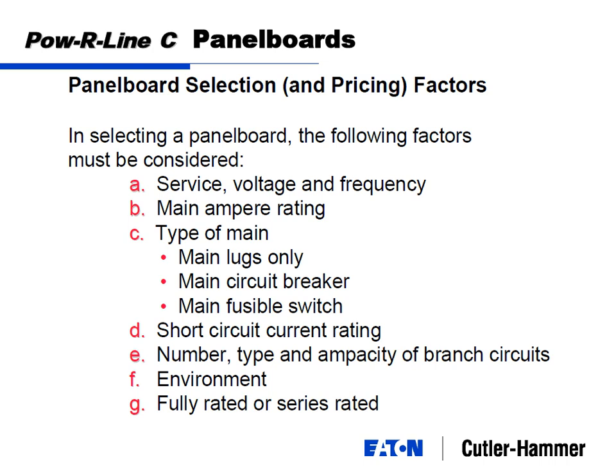What's he talking about, this bypass, where you take the meter and you bypass the meter just for service? Oh, yeah. That's meant for bypassing the meter, for service, not to disconnect the building, at least the way I understand it. Yeah, that's for when I need to pull the socket out and put a new socket out. Like recently, most people had the electrical mechanical meters with the dials, and I think they went out and swapped those and put the new solid state ones in, or digitals. So pretty much that's all that's for. It's not really a pure safety service entrance that you can lock out, tag out, or anything like that.